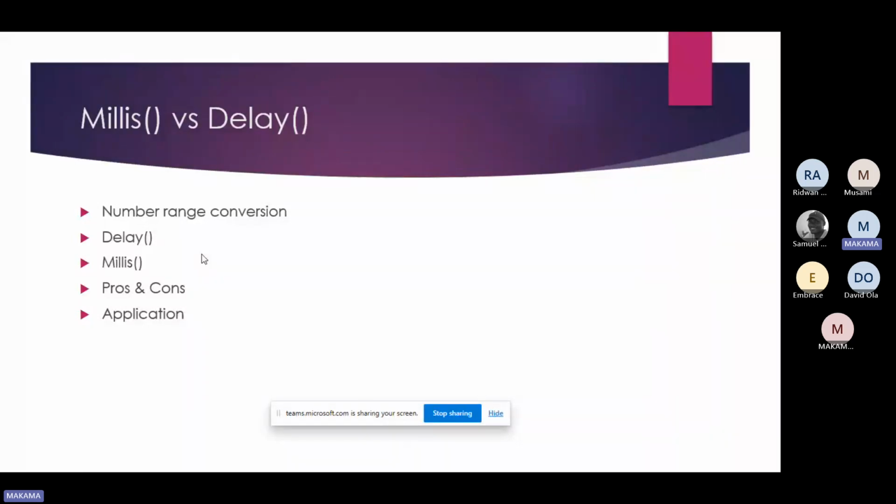So you can use that millis function in a way that you get rid of the delay function, and your LED can be paused and on, paused and on, without affecting the rest of the activities of the microcontroller. I'm sorry I've spoken much on this one.